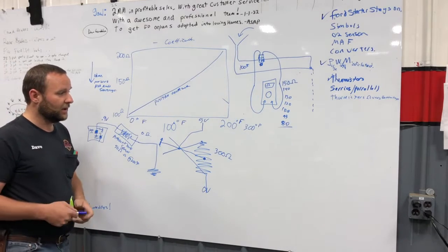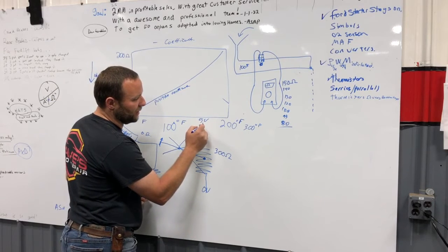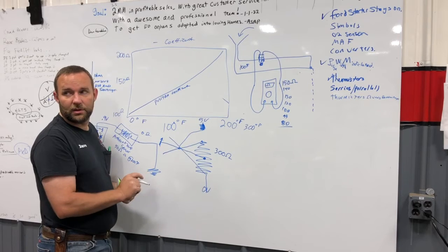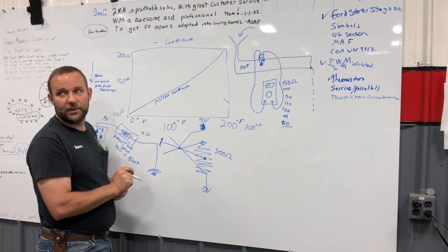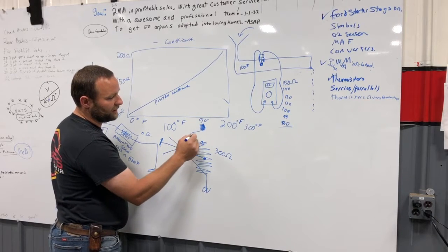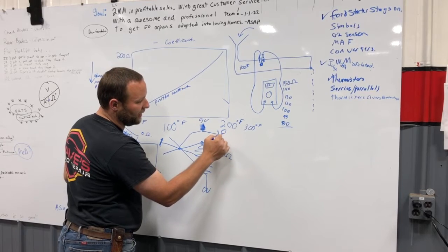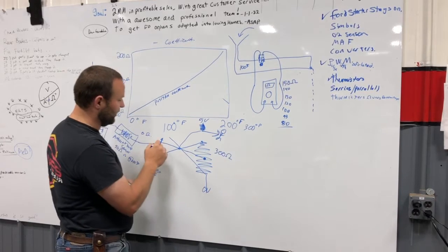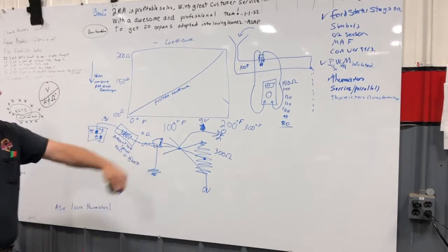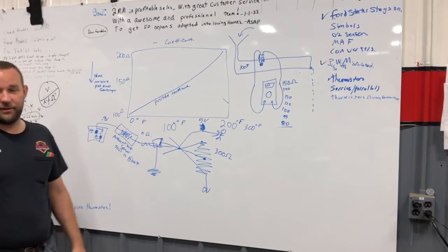So you'd have to have another resistor up here to get a voltage change. A fuel gauge, you'd have to have a resistor. 5 volts, a resistor, and then you go down here, and this voltage here varies. This here again is the comparator, and he's looking at that. Let's put a little float here. Based on fuel level, it changes resistance, and that's how a fuel sensor works in that car right there.